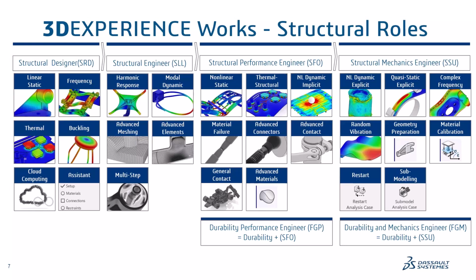And you can move up a little bit from there into Structural Engineer, where we've got modal analysis, modal dynamics, harmonic responses, a few other bells and whistles. You can start doing multi-stepped loading. And then where we get into above and beyond SOLIDWORKS simulation tools starts at Structural Performance Engineer. That's where that nonlinear solver really comes in. Advanced material models for sure. Nonlinear dynamic implicit solving. And if you've got to go faster than that and do dynamic explicit, Structural Mechanics Engineer at